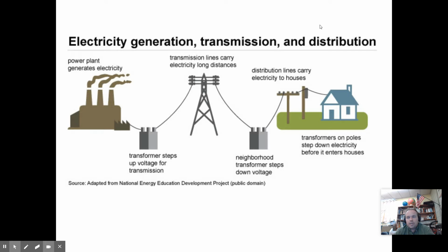And so, of course, when we're thinking about solar generation, we're thinking about DC. When we're thinking about wind turbines, we're thinking about DC. We have to convert those to AC, or actually, rather, invert those to AC power to be able to run any of our appliances, because that's how they're designed to run. The advantage of AC is that you can transmit it over long distances without having to have really thick wires with high amperages.